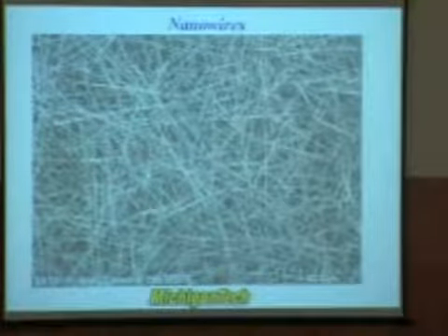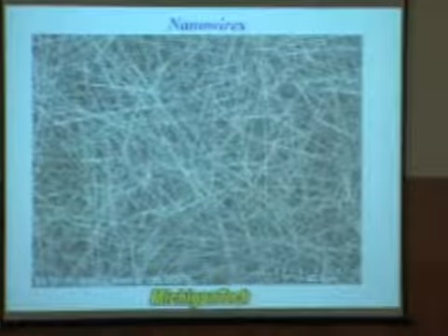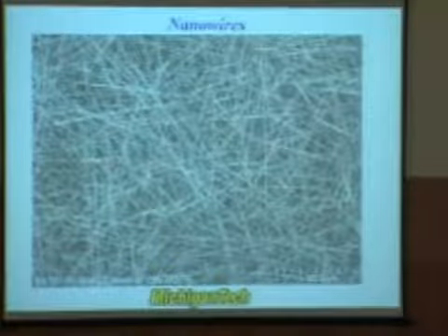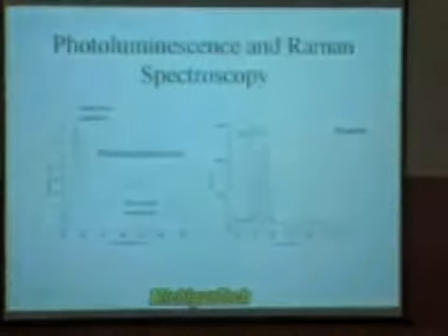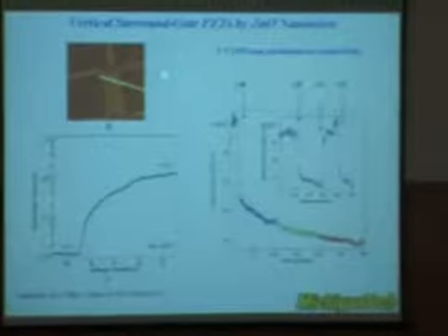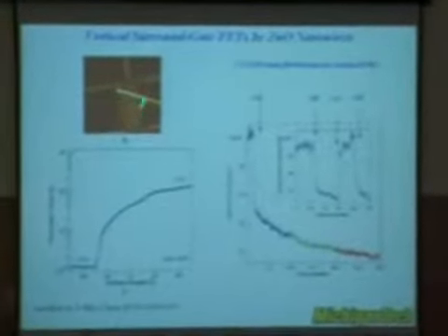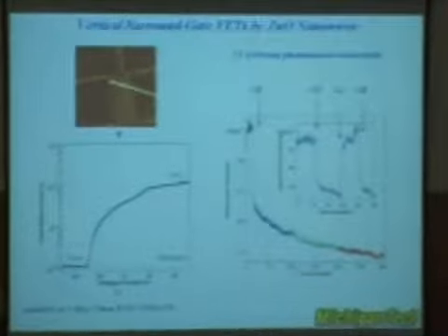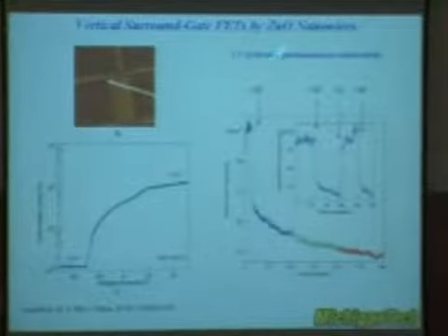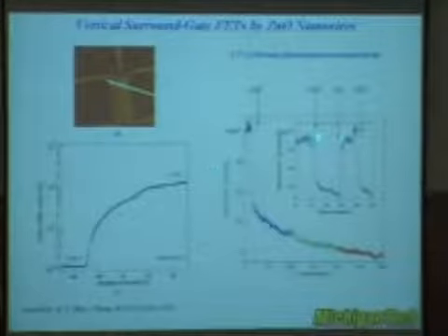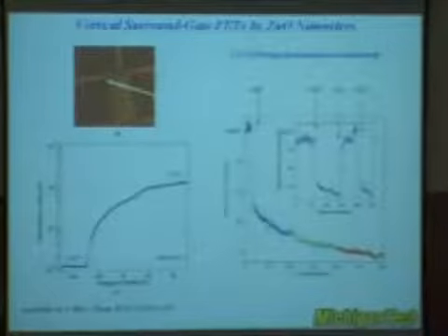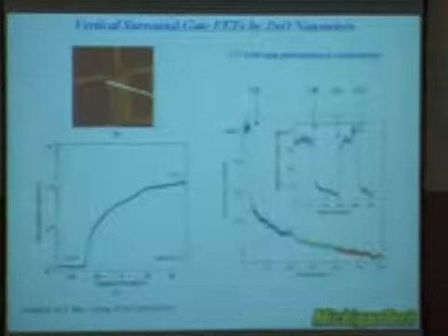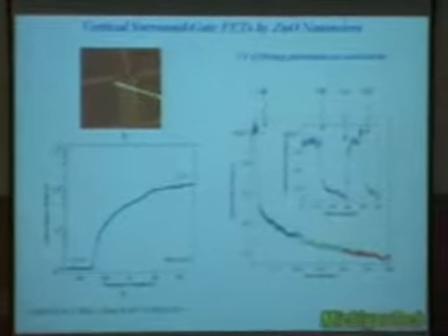This one is grown at 500 degrees Celsius. Absolutely compatible with CMOS technology. You can directly grow them across the electrode if you want. All right, just skip some of them, and actually it was already demonstrated in 2003 using a piece of nanobelt, which demonstrated the on-off state. And also, it can be used to sense UV light, actually. And you can see that if the light turns off here, you can generate the so-called photoelectrons inside the zinc oxide materials. So device, no problem, you can use it.